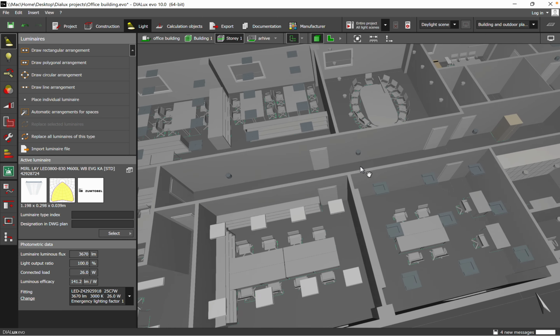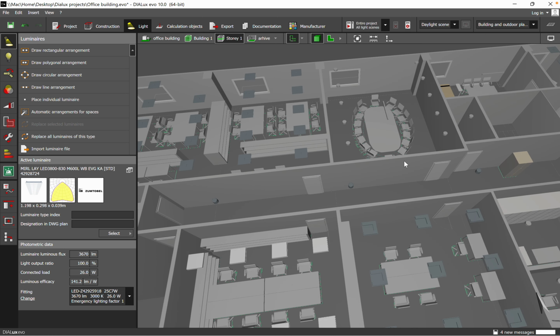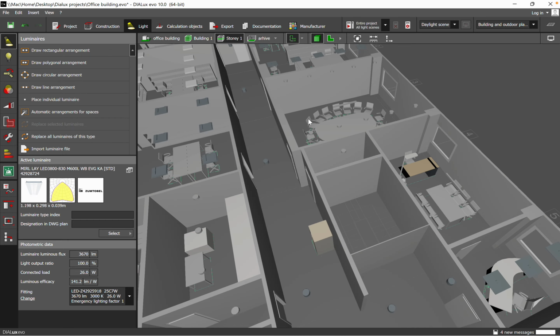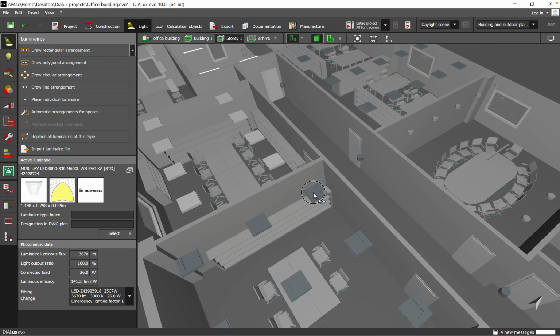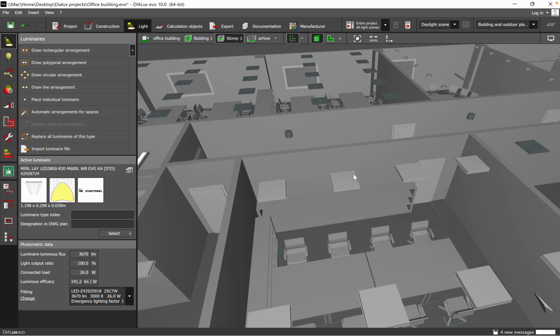Unfortunately, personally, I'm not recommending this kind of totally indirect lighting. Even though you eliminate the cave effect and reduce the glare drastically compared with direct lighting, even the direct lighting is according to UGR below 19, so it's also comfortable in accordance with the norms for fulfilling the lighting requirements for an office space.